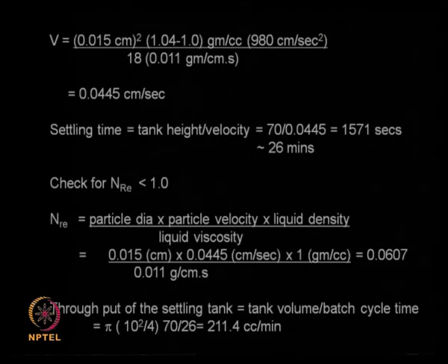So Stokes law depends upon dilute solutions, that means the solids that are settling down are not disturbing or impeding the other solids that are present. One solid may affect the movement of another solid either through collision or creating eddies or turbulence, then we cannot use the assumptions of Stokes law. That means if the concentration is very high we cannot use Stokes law. If the velocities are very high in the form of turbulence, then again Stokes law is not valid.